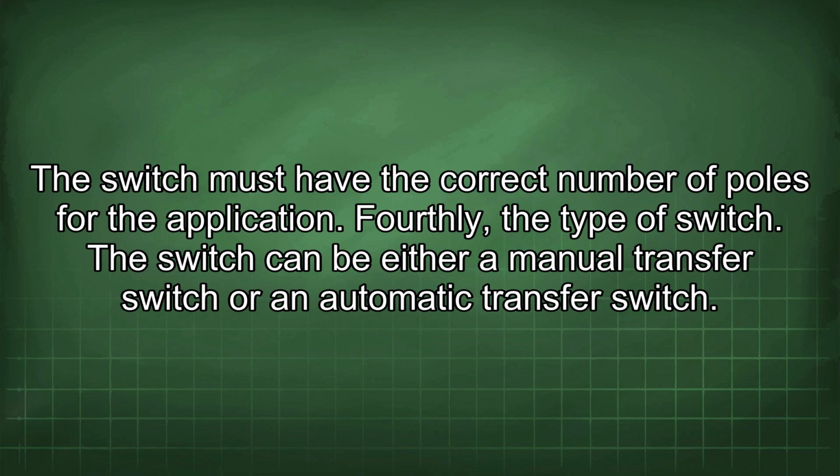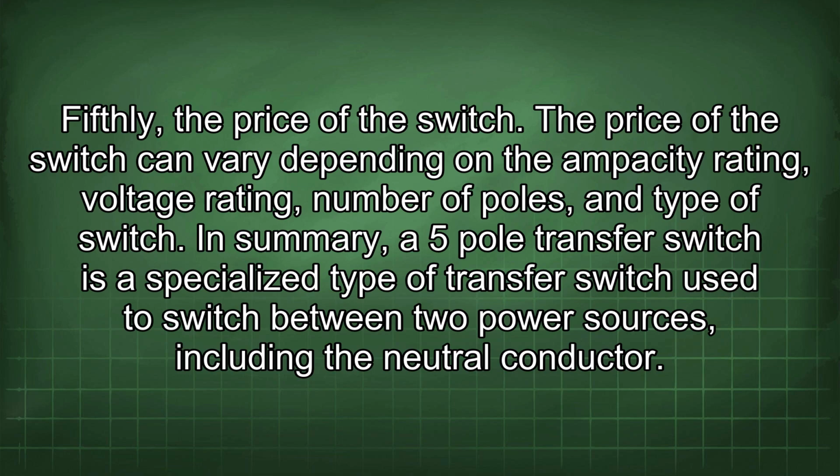Fourthly, the type of switch. The switch can be either a manual transfer switch or an automatic transfer switch. Fifthly, the price of the switch. The price of the switch can vary depending on the ampacity rating, voltage rating, number of poles, and type of switch.